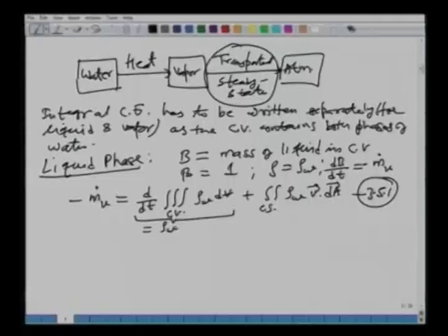All right. d by dt of your volume, total volume is A times H, where A is the cross sectional area and the rate at which the height is reducing is dH over dt. Okay. So, if you take the rho w out, you have the volume V, all right. So, you have A dH over dt. So, overall if you see these two things, the units will be the same. So, the first term will be equal to rho w A dH by dt.